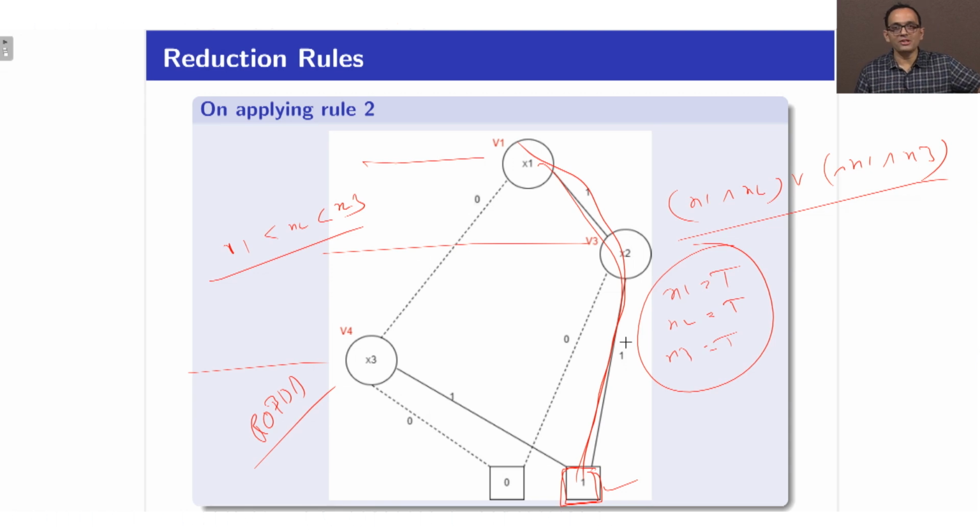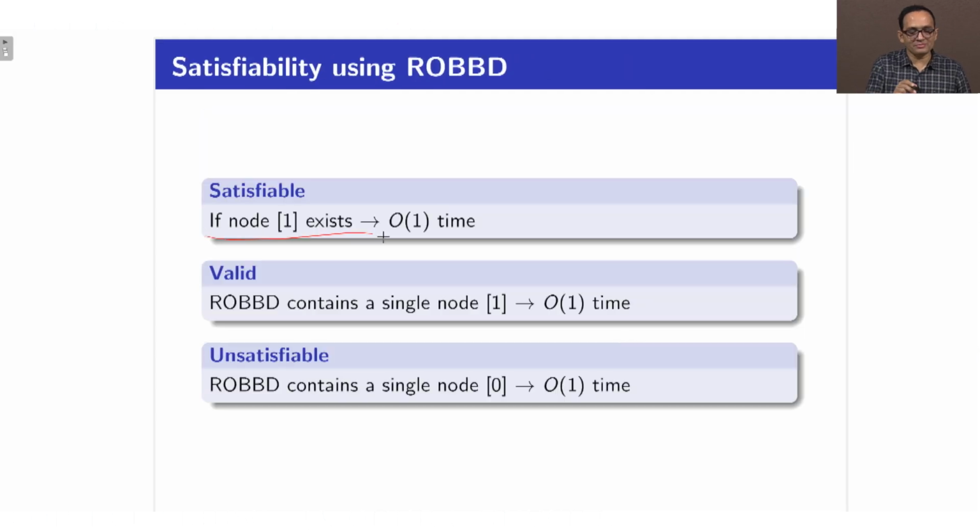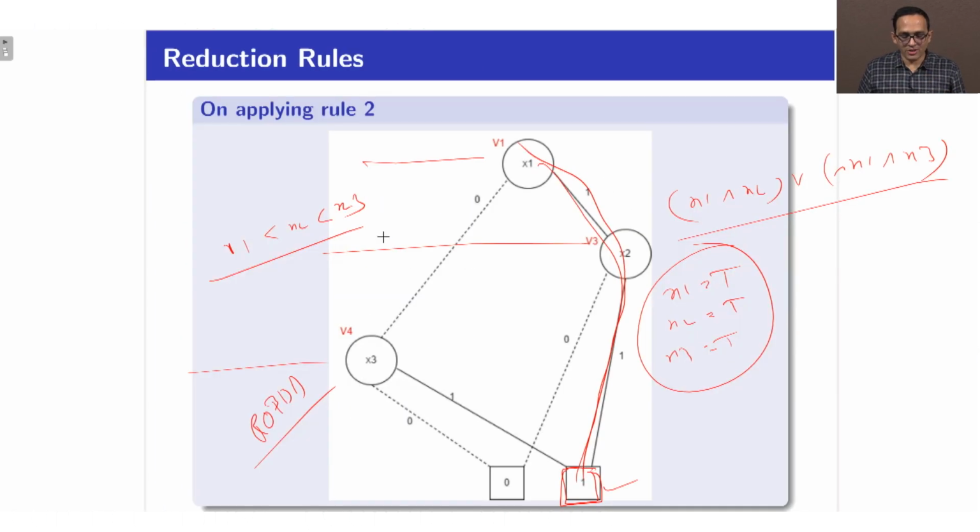On the other hand, you have seen that in SAT solver it can be NP complete, right, 2 to the power n. So, you might get confused now that does it mean that you solve the NP complete problem in polynomial time? The answer is no. In subsequent classes, we will see that the size of the ROBDD is very much sensitive to the variable ordering. Okay. So, if you take a good ordering, you get a good BDD, and you can actually get your satisfiability in order of n time, right.